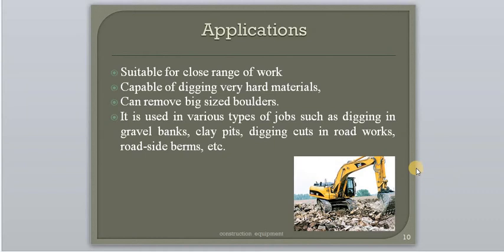What are the applications? It is suitable for close range of works, because it cannot travel from one place to another, because there is a chain here. So in nearby areas we can use it for excavation. It is capable of digging very hard materials. It can remove big size boulders also with the help of this power shovel.